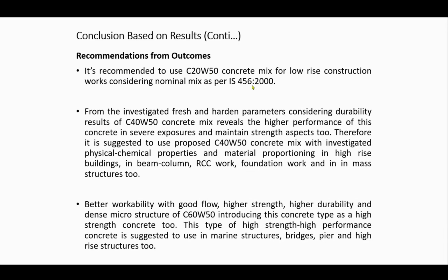Yes, from this research, from this discussion, I can say with confidence that you can use that waste for low rise construction. From the investigated fresh and hardened parameters, considering the durability results for 40°, we can say that this mix reveals higher performance of this concrete in severe exposure and maintains the strength aspect too.